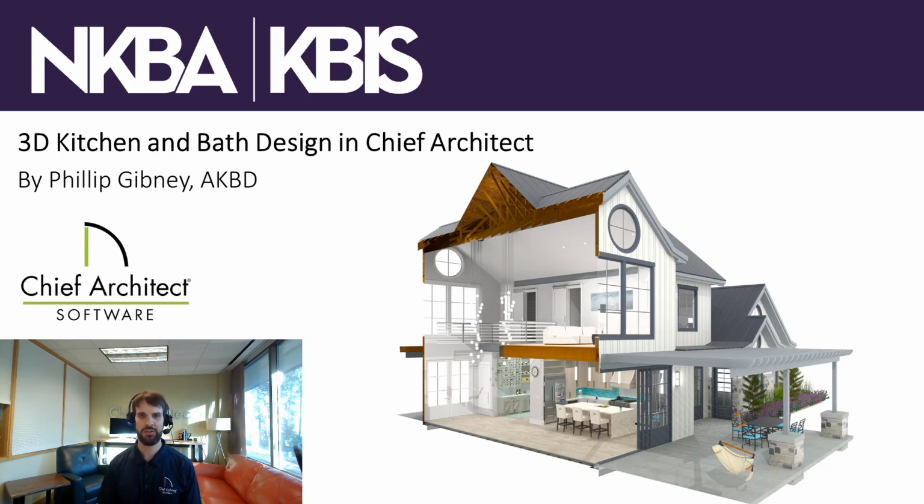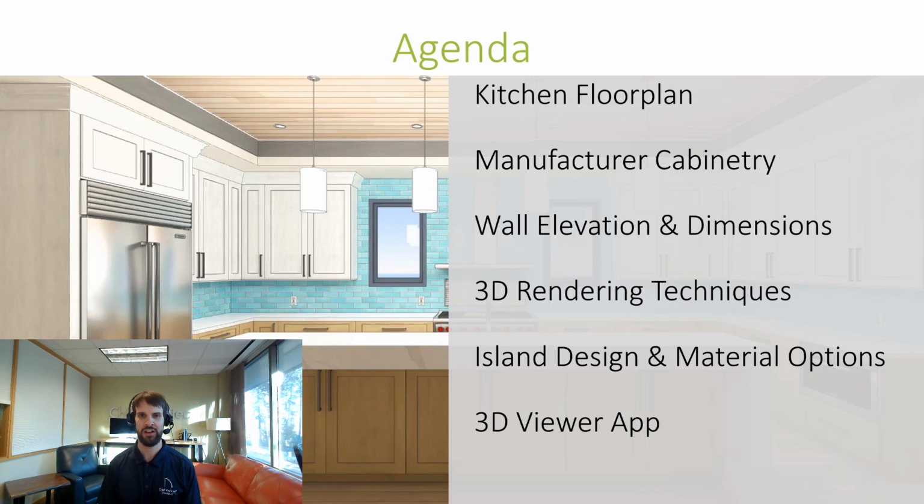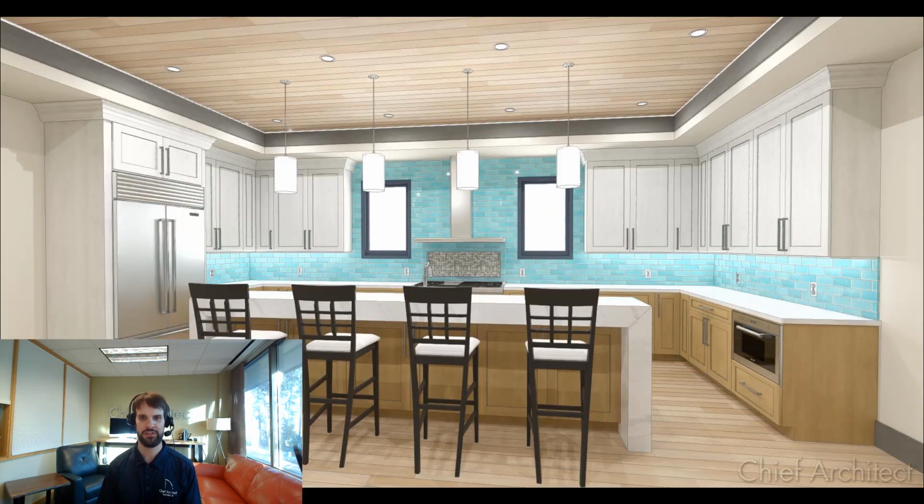In this webinar, we're going to be using the actual software to create a kitchen design, and we will start by creating a kitchen floor plan, then take a look at how to design custom manufacturer cabinetry. We will create a wall elevation and automatically dimension it, and along the way we will be using 3D rendering, and later in the webinar we'll take a look at the different 3D rendering techniques available. We will also take a look at how you can use the software to provide your clients with design and material options in the example of an island, and we'll wrap up by taking a look at ChiefArchitect's 3D Viewer app. And here's a rendering of what the final design we will create today will look like. So with that, let me go ahead and switch around to Chief and let's get started.